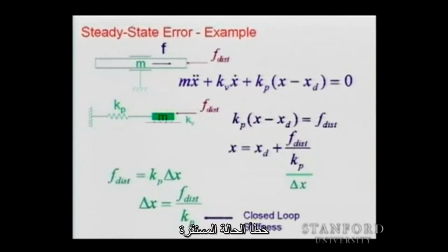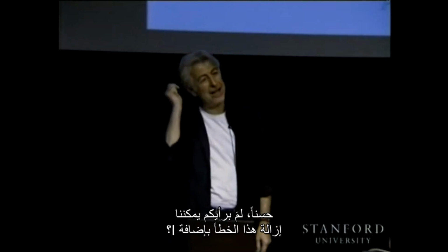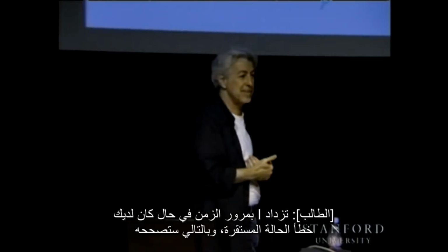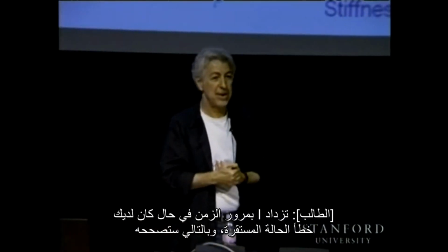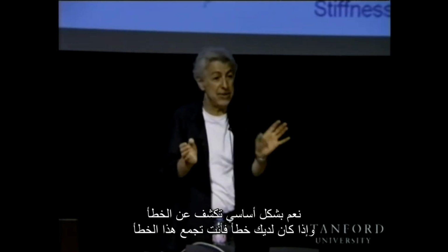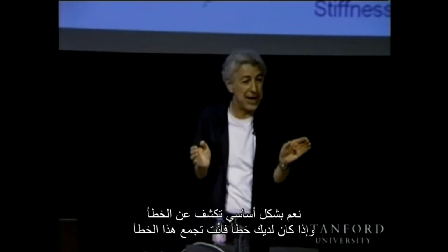Okay, now how can you get rid of that error? The steady state error. Yeah, I know, I hit that slide now, you know. You don't know. All right, go ahead. You can add an I. Yeah. Do you think he didn't see the next slide? No, you didn't see it. Okay, why by adding I can we remove that error? Because over time the I grows large if you have a steady state error, and it'll correct for that. Yeah, basically you detect the error, and as long as you have an error, you are adding.